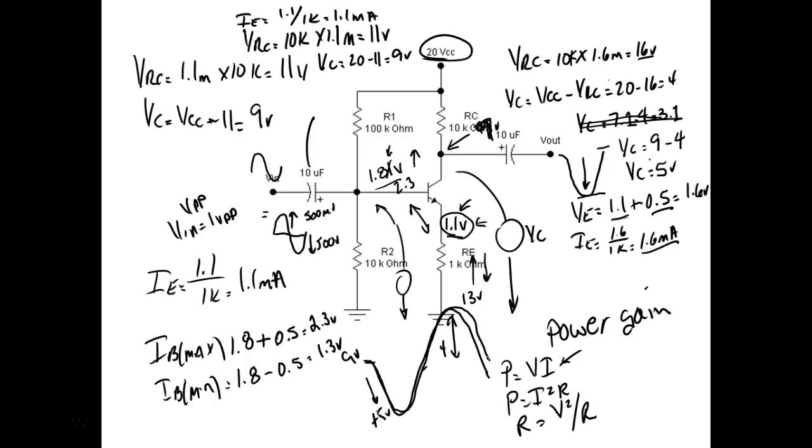So how could we have calculated the gain to start out with? This is where your output is actually changing right here. Your input is felt across this resistor. Your output is felt across that resistor. And how do we calculate gain, guys? Out over in. So here we would use V out over V in, right? That makes sense?